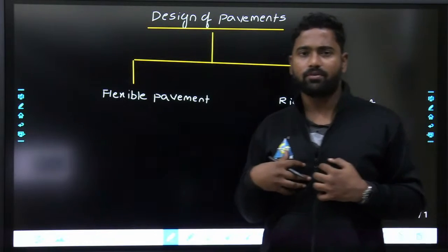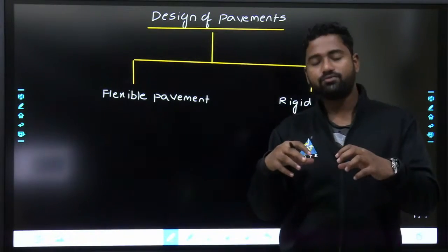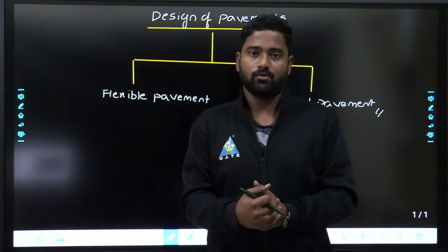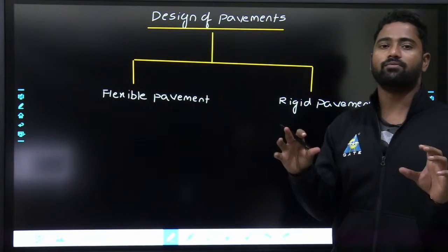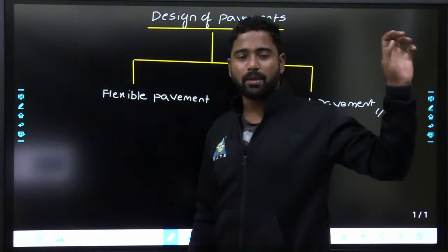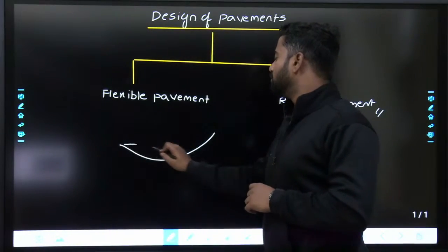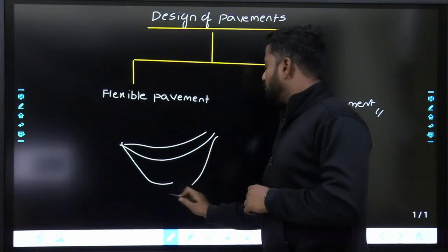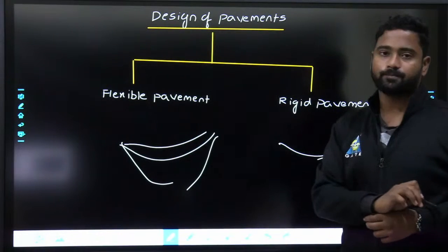We generally prefer ductile failure. Why do we prefer ductile failure? Because it gives you indication before the failure, whereas brittle failure will not give you indication, it will directly fail, right? That means if you take normal beams or anything, there will be a huge amount of bending before failure, whereas here there will not be any bending, it will suddenly fail.